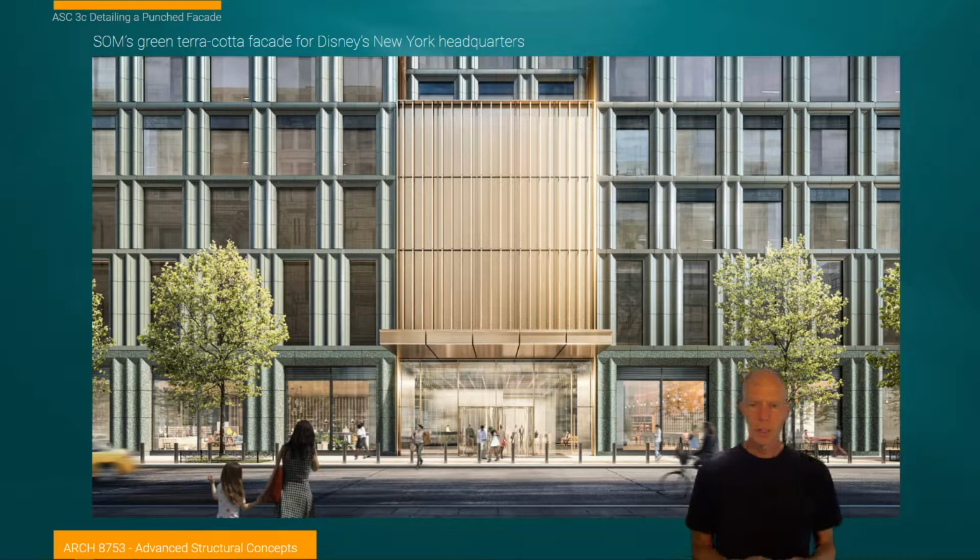The first punch facade I want to show you is a stimulus towards this idea of thinking about punch facades. I'm going to focus, leading up to the project, on terracotta because of my experience with it and because of its fluidity in creating all kinds of forms. But we also realize it has a heavy carbon footprint. You may decide that you want to use another material. You can use metal, thin porcelain materials, or thin granite materials. Really, anything you choose would be quite fine in this project. But for the discussions going forward, I'm going to talk about some terracotta projects and the manufacture of terracotta.